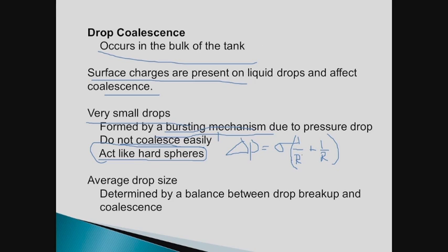Now, when this radius gets very small, 10 microns, 50 microns, 2 microns, and it divides into surface tension, there's a huge pressure increase across the interface of a drop. Same thing for gases as well. There's a huge pressure increase as you cross over the interface of a drop or bubble.